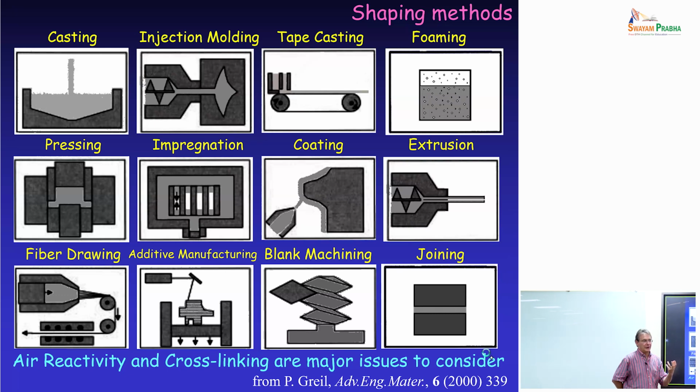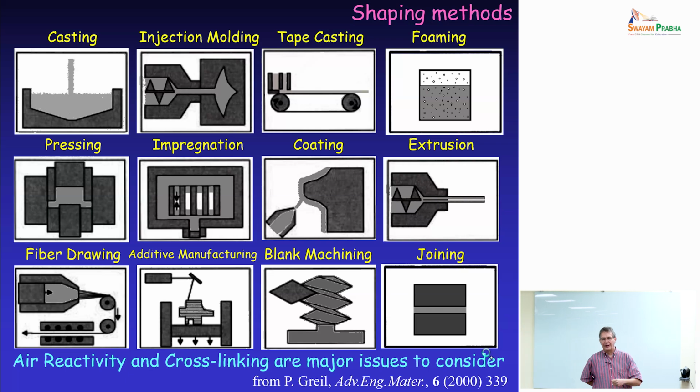So one of the advantages of having a polymeric part is that you can machine it before pyrolysis. So you can obtain parts that have interesting shapes in this way, with all the defects or limitations of subtractive technologies. And one interesting possibility is that you can use preceramic polymers for joining.